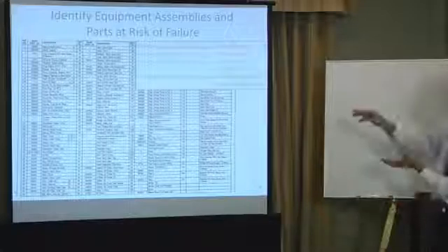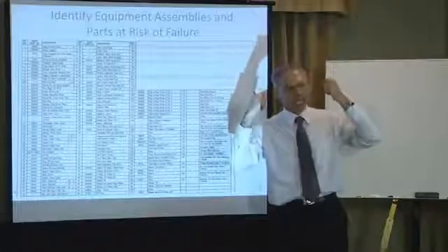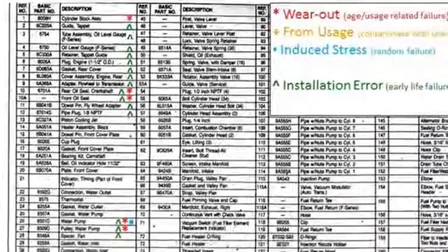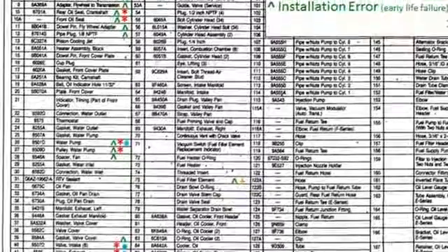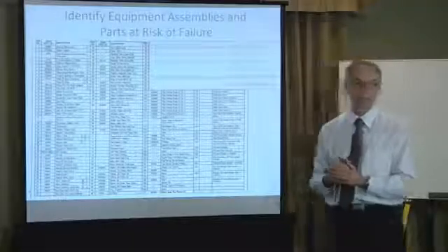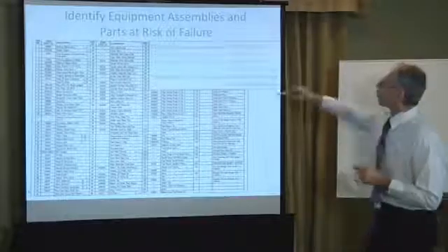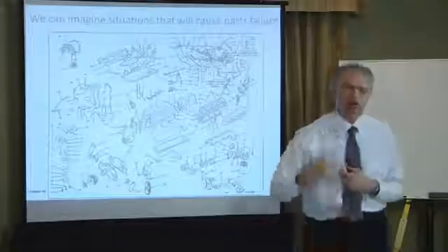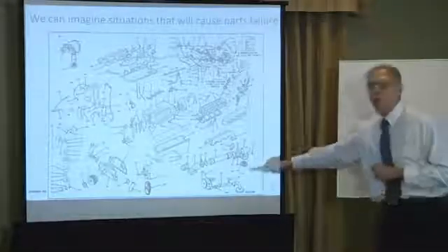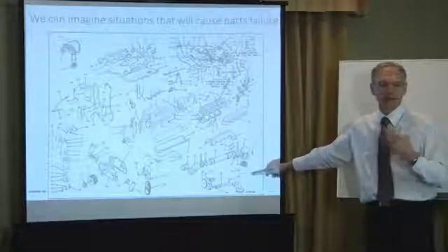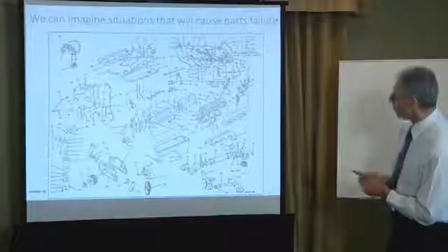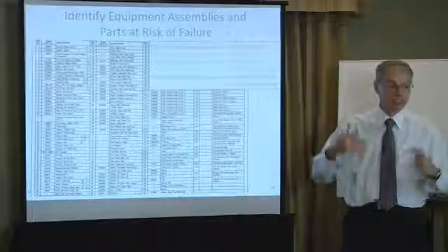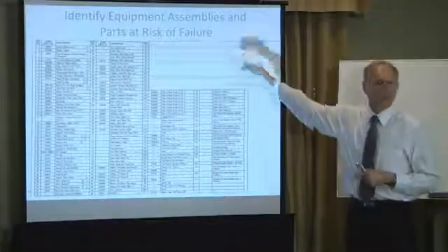So I can now take my parts list and put on my stress manager's hat and say, okay, which of these parts are going to wear out from use? In which case, if they're going to wear out from use, I'm going to inspect them on a regular basis to see how quickly they're wearing and track that and trend it and monitor that. What parts will actually degrade from use? What parts are intentionally going to fail by their service? Here we go, oil filter. That filter will degrade intentionally by use. And there's a fuel filter in there as well. So any parts that by their use will be contaminated and will degrade on purpose, it's designed that way, well, I want to renew those at a particular frequency.